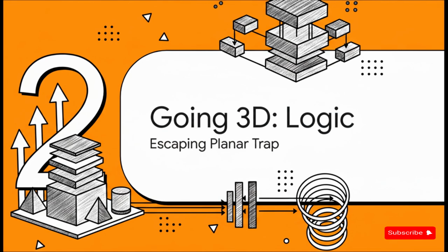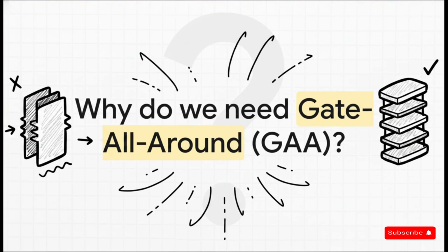Which brings us to Section 2, going 3D, logic architectures, or escaping the planar trap. To solve those massive leakage problems we just talked about, the industry had to completely rethink its geometry and take logic designs upwards into the third dimension. For years now, the industry standard has been the FinFET. It's a 3D tri-gate transistor, and honestly, it totally revolutionized the field.